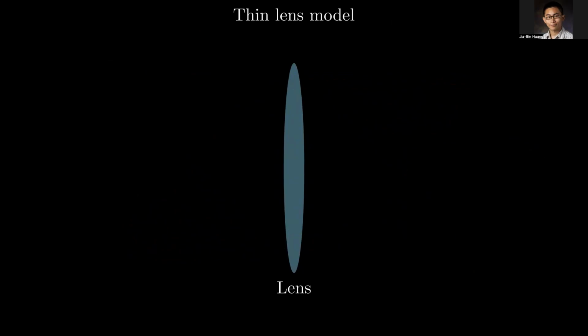Why couldn't you just artificially make it brighter by scaling the values, just multiply it by X? You could, but every sensor has noise. Every pixel is trying to count how many photons hit that particular CMOS sensor. If not a lot of photons hit those pixels, you will have a lot of noise.